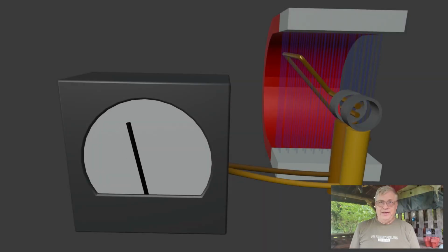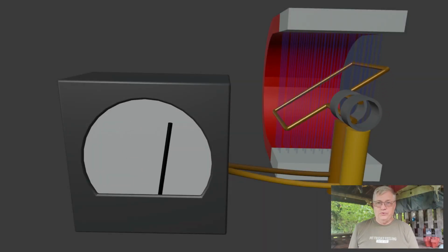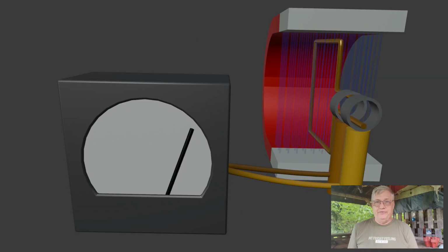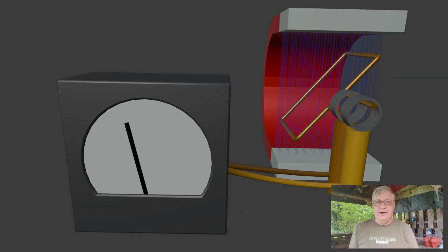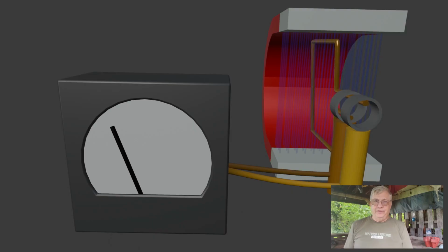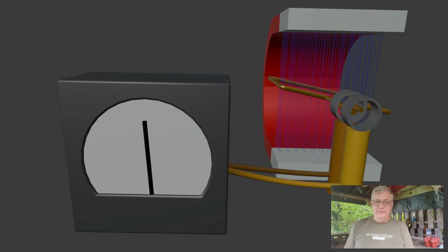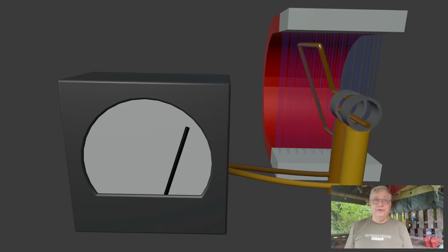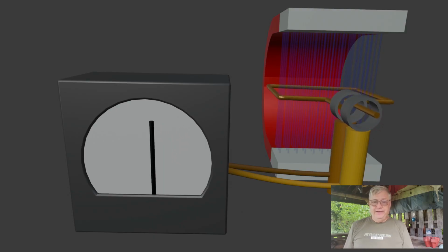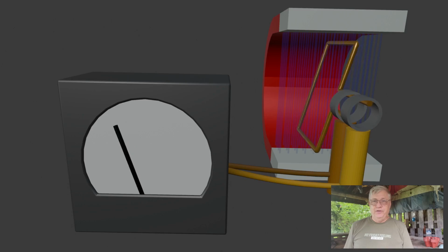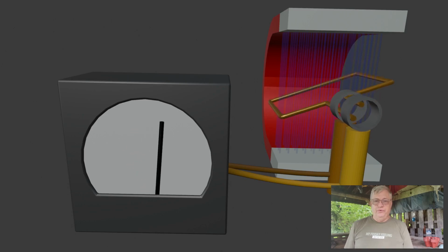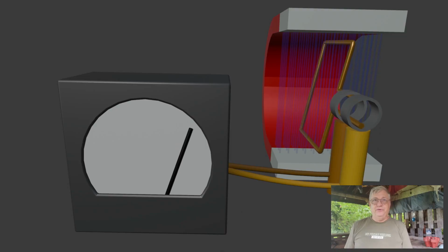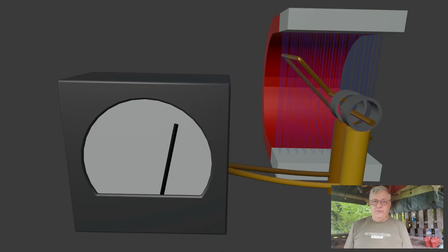To better understand AC, or alternating current, let's talk a little bit about a simple alternating current generator consisting of a magnet and a coil of wire. We have a little illustration up here on the screen for you to look at. When we spin the coil within the magnetic field, when the coil is horizontal to the magnetic field, it's cutting very few lines of force.